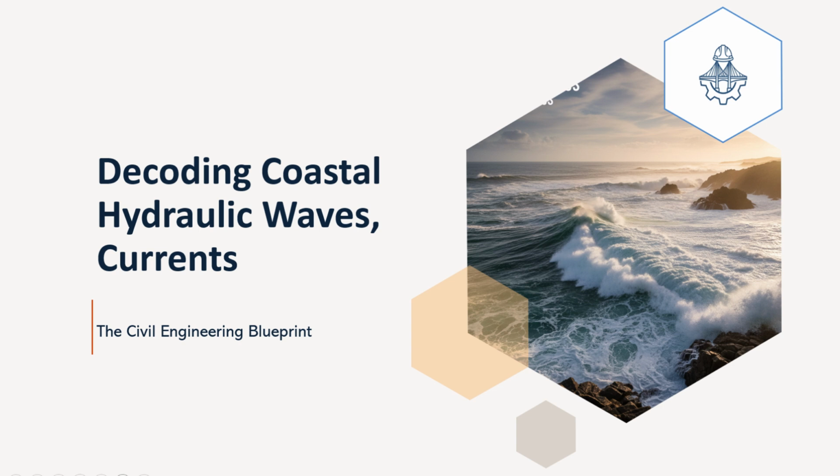Our source material even provides specific local data on sea level change due to tide off Colombo Port. It shows things like the annual maximum and minimum tidal heights recorded over several years, as well as the annual mean sea level variation. This kind of localized tidal data is absolutely crucial for practical engineering applications. Tides directly influence required water depths for navigation, the necessary design height of coastal structures like seawalls or docks, and flood protection levels. You need local data.